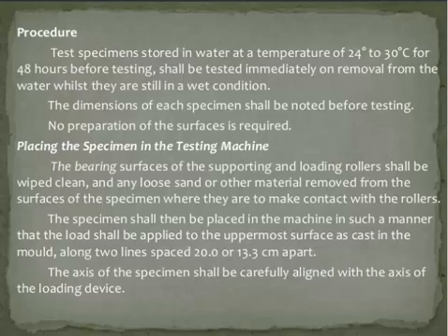Then loading is applied, applying loads between 2 to 6% of the computed ultimate load, employing 0.10 mm and 0.38 mm leaf type filler gauges. Specify whether any space between the specimen and the load applying or support blocks is greater or less than each of the gauges over the length of 25 mm or more. Marking is done on the specimen.